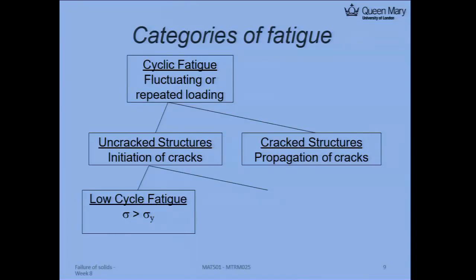For this type of fatigue, you have something called low cycle fatigue, which means your cycle life is very short, very low. That means your structure fails very early, just because you apply a stress close to or even higher than your yield strength. So basically, you fail by reaching the yielding point. That's why you have fewer cycles. But by contrast, if you apply a very tiny load, for example 10% of your yield strength, you will reach a very high cycle number. It takes probably years to fail a sample.